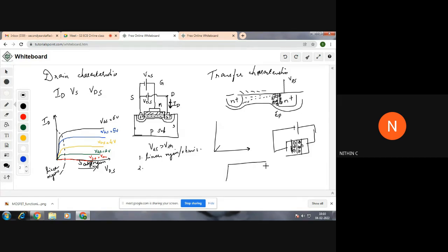That's all there is to it. When you normally draw a PN junction, you know that when you are reverse biasing, your depletion region width will increase. When the depletion region width increases, you only need to think about the immobile ions formed on the N side. What forms on the N side are positive immobile ions. You know that; look at the old figure to get an idea. You will have positive immobile ions. So these positive immobile ions will drag the electrons to the drain.